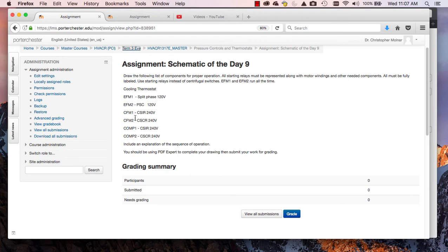We have an outdoor unit with CFM1, CFM2. Okay, now, this schematic is going to get a little strange. You have an option here. We could throw a contactor in here, which we might actually do to cycle the outside unit and use 2 different power supplies, or you can run part of the 240 volt circuit outside. I am not a fan of that. I like having 2 feeds, so that's probably what we're going to do in this case.